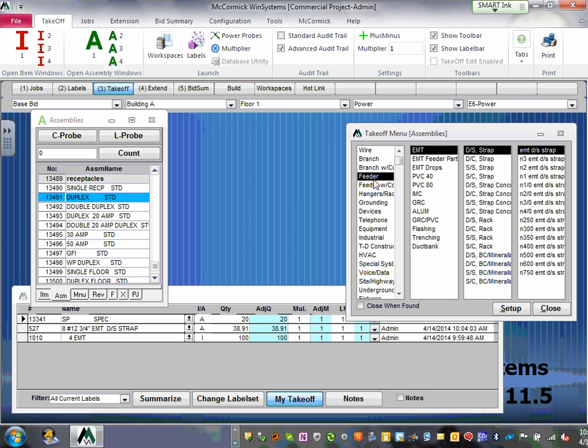Remember, we're moving with 6 circuits in a conduit. We're going to group the circuits, put boxes in the ceiling, and take MC cable to the ceiling and pull them all the way to the panel. If you're in the walls, you can move with MC cable in the walls. We're using a metal stud, so you can do this for all these rooms.